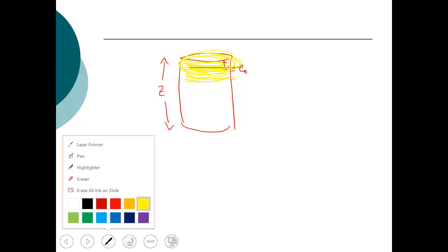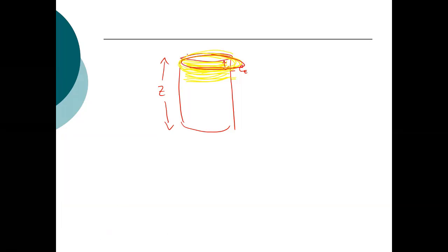You've exhausted this portion of the column. And why is it not changing back to red? Okay, so you've exhausted this portion, and that moves down. Then you exhaust this portion here, and your adsorption zone moves down the column until you get to the point where the concentration leaving the column is 95% of what's entering the column.